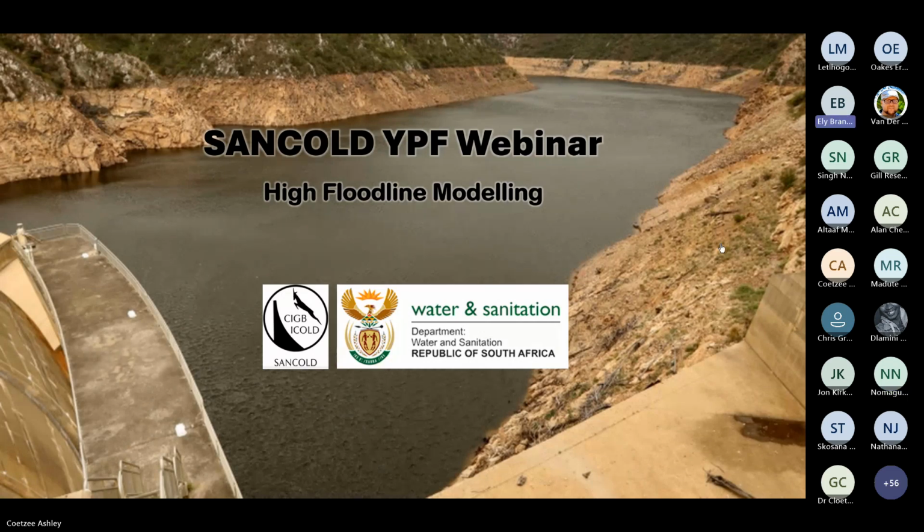Okay, you're welcome. Can I please just come in, Brandon? Just a little note from our own experience. In terms of the extent of the spatial data, it can be a bit of a subjective thing as to how big your terrain and your 2D area should be. But an important thing is to make sure that when you've done your simulation, the water is contained in your 2D area and you don't get any spilling out of it.